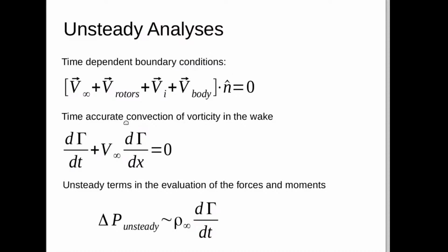Instead, as you step through time, you think of time zero with a wing in a tunnel, and you turn on the tunnel. The wake starts to shed as the time goes by. That wake starts to move downstream, and initially the wing is generating no lift. At some point, it's generating some lift, and then that lift, as time goes on, hits some steady state value.